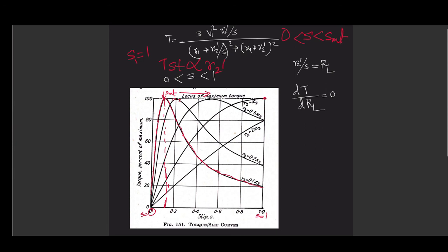If you do not have any closed circuit in your rotor, there will be no flow of current through the rotor circuit and there will be no torque. But this expression seemingly indicates that it will give us an infinite value of starting torque if we keep the rotor circuit open. So where is the fallacy, that we will discuss in our next video. And if you apply your logical sense, you can also figure it out by yourself.